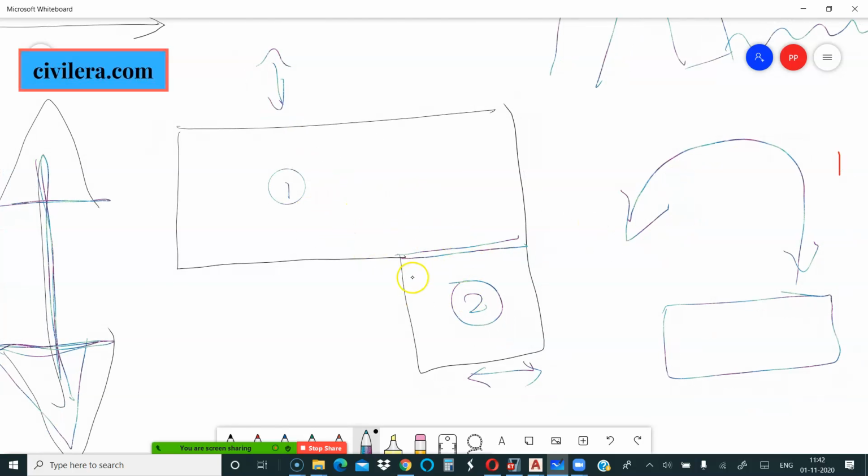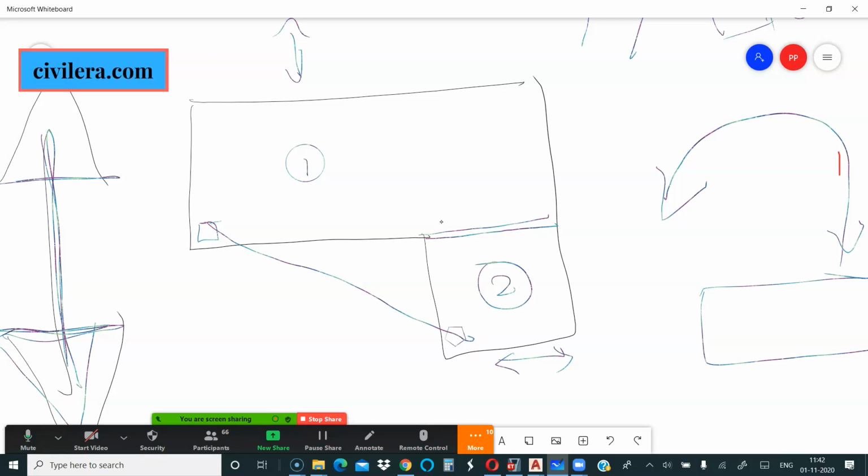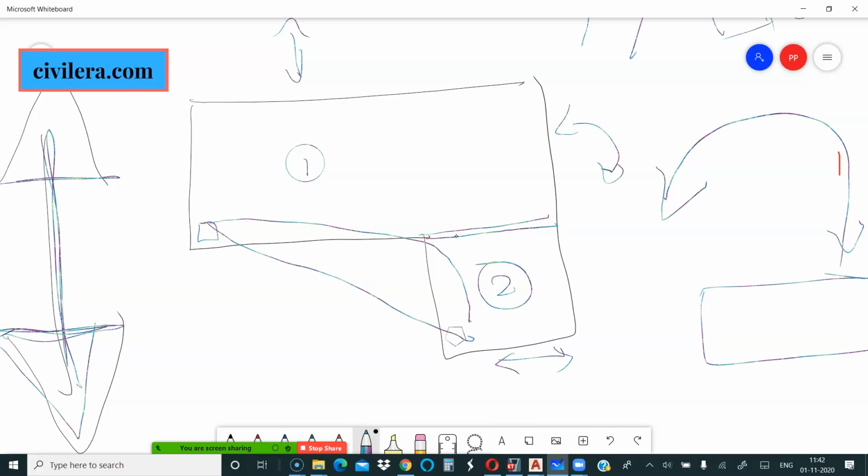So it is regular. When you have an irregular building, the problem is you have a column here and say you have a column here, there is no direct interaction path between them. So it interacts in a concave shape, which means your building is going to rotate. That's why the torsion is getting generated. All your slabs are interconnected, so it is all stiff. So the interaction is like this. Yeah, so any concave shaped building like L shape, plus shape, all these are not so great from a seismic behavior point of view. So that's why you better separate that into multiple buildings with joints.